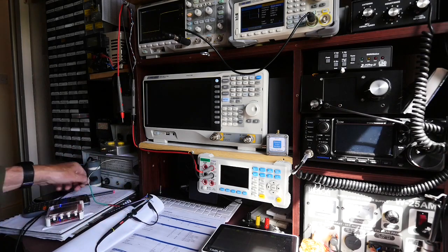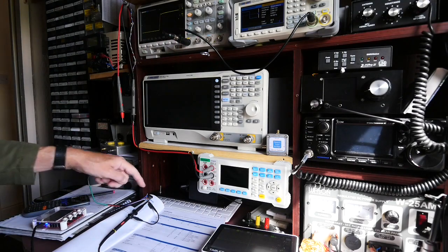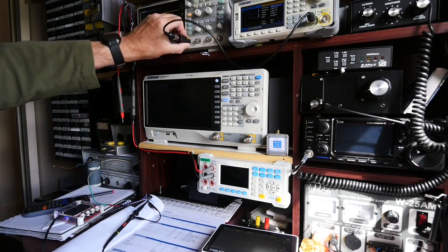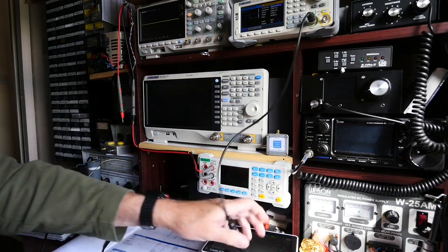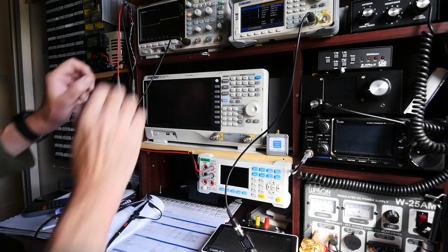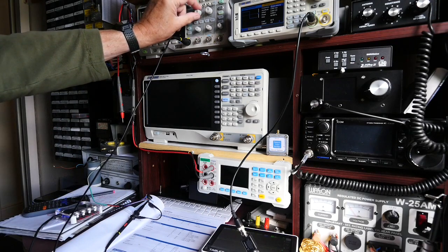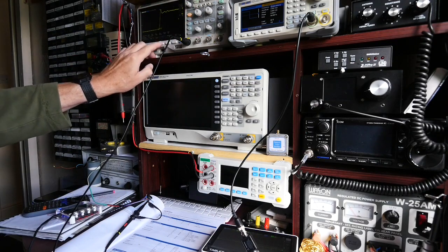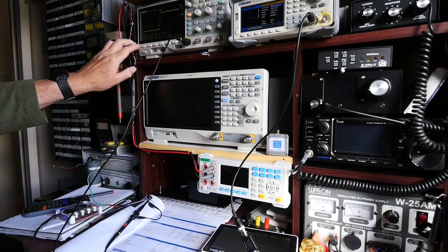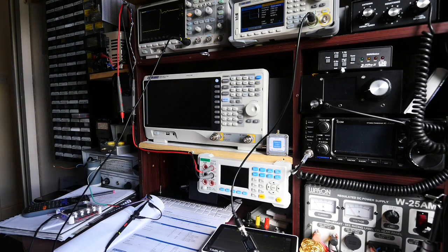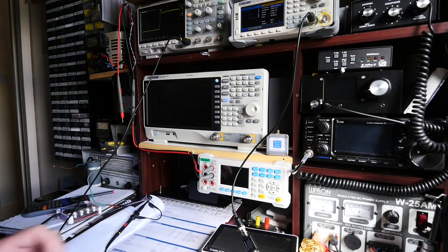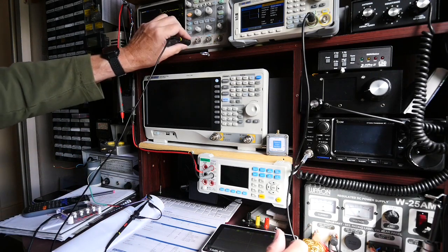So it's very fast indeed. So if we now swap from the signal generator, and that oscillator just happens to run at about 16 kilohertz, that's why I've picked 16 on the signal generator. So if we now pop that into the Siglent, and we'll just clear the statistics again, we're getting a rise time there of about 3.72 nanoseconds mean, something like that. Again, we'll put these numbers into a table in a minute and talk about them.